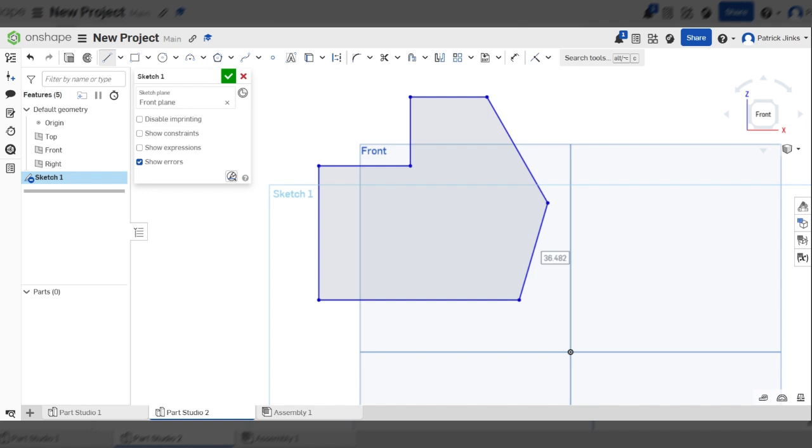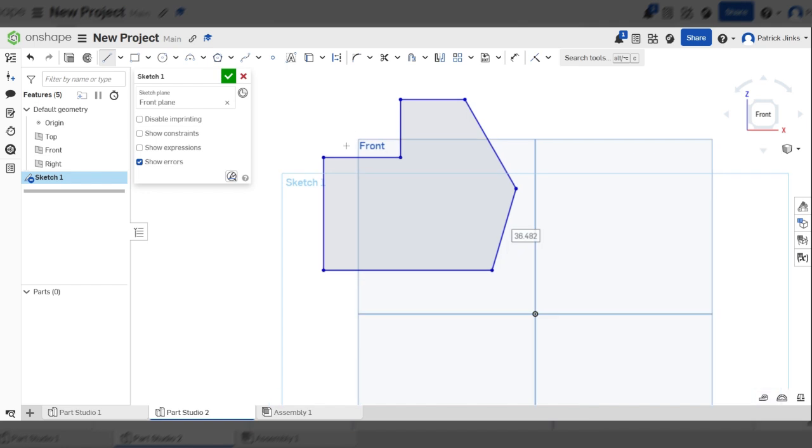However, the first thing I'm going to show you today is how to put a fillet on a sketch. And I will be honest, it really doesn't matter too much whether you do it on the feature or on the sketch. If you do it on the sketch, it can get less complicated later on. So all you're going to do is go across the toolbar and click on this button here. It looks like a corner with a curve on it. It's called the sketch fillet.